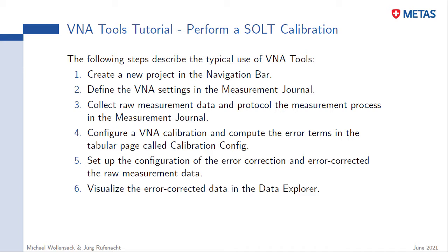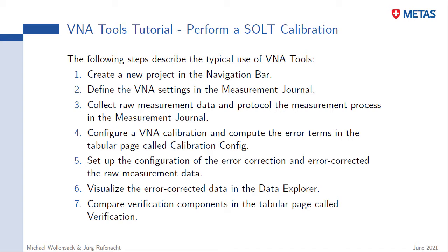Sixth step, visualize the error corrected data in the Data Explorer window. And finally, the seventh step, compare verification standards by using the verification calculation feature of Vna tools. This will calculate the complex difference and the normalized error based on the reference data.